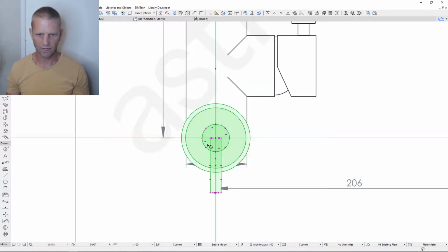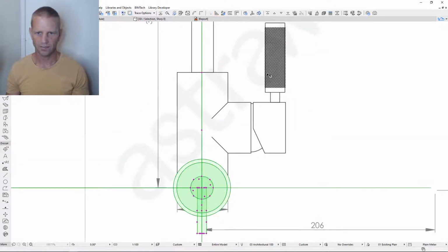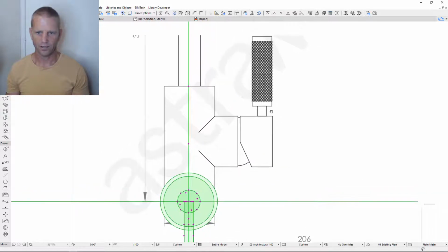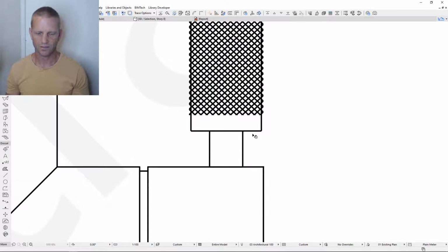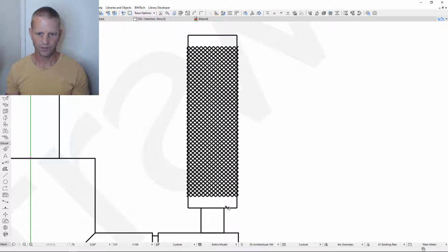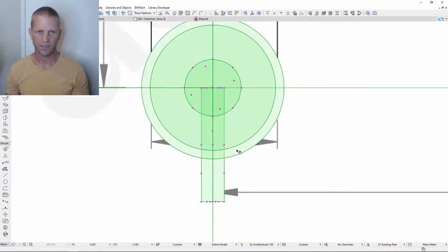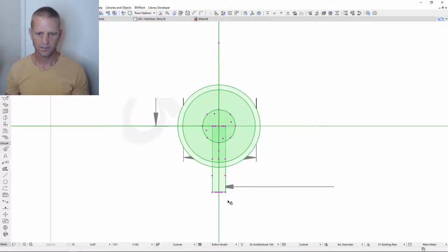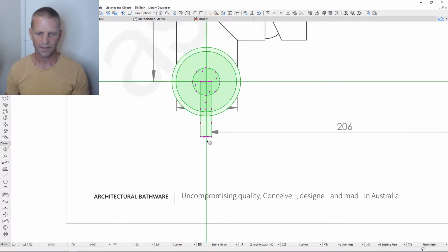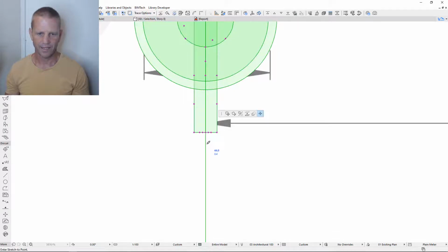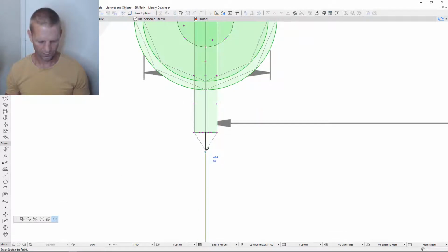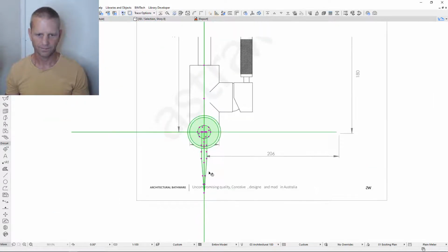So you can see we have this one element here that's got its y-axis at 0, so that's why we can access it. And it's actually the lever. So it's actually this element here. So I've measured this element and we've got values of 32 and 92, and that's 8 mil and that's 17 mil. So we're just going to go in and set up this one first. So let's take this node out to that 92 mark. So that's going to be the full length of our lever.